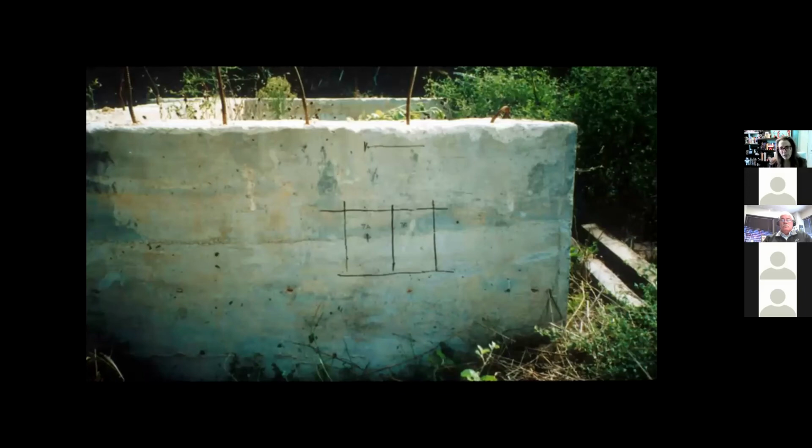And so depending on the age of the concrete and the strength needed for bond between layers to make it a monolithic structure, and depending on the amount of reinforcement in it, then the engineer can decide what that minimum bond strength might be. They might ask for 1,000 PSI, they might ask for 2,000 PSI, it depends on the structure. But that's how you would fix that. And then if you needed a better bond, you don't need to tear down the structure, you inject that cold joint with some sort of crack repair. Typically an epoxy or cementitious grout. If it's just a pour line, it's just unsightly.